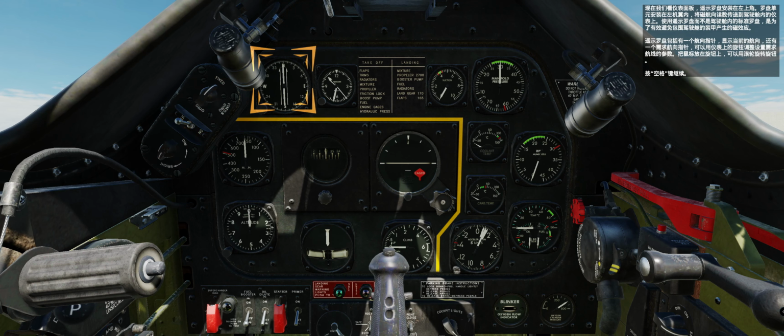Moving on to the instrument panel, the upper left corner houses the remote indicating compass. The compass unit is installed inside the left wing and transmits magnetic readings electrically to the cockpit indicator. Using a remote compass avoids the magnetic effects caused by armor plating around the cockpit, experienced by a standard magnetic compass.